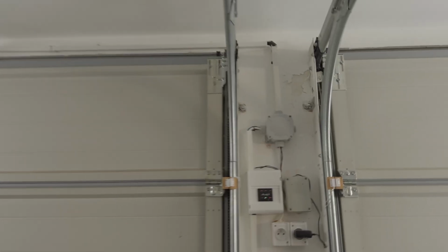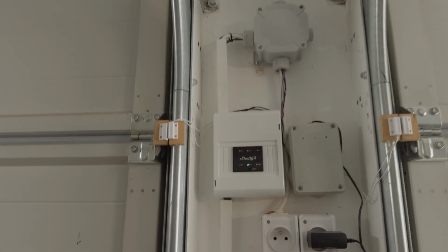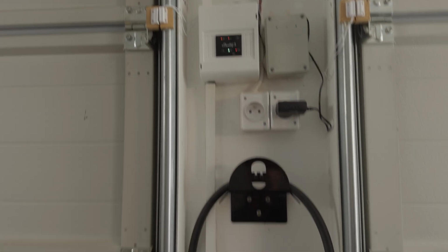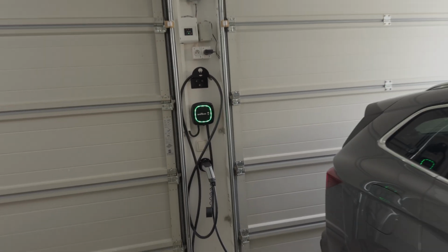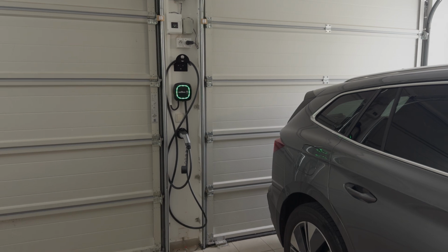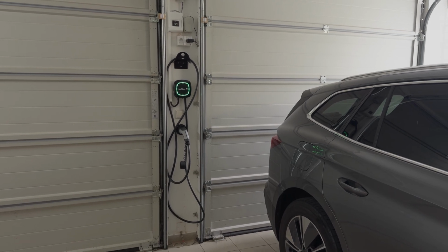it's not connected to the wallbox directly. There is a Shelly 3 Pro, which is a 3-phase small switch, and that only supports 16 amperes per phase. So it will only support 11 kilowatts, but it's connected to a 16 ampere circuit breaker anyway, and I configured the wallbox to limit the current to 16 amperes, so we're fine.